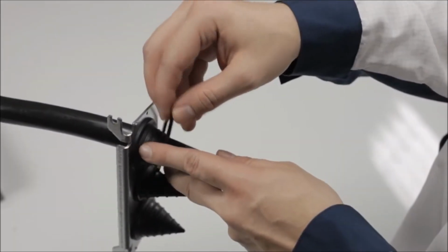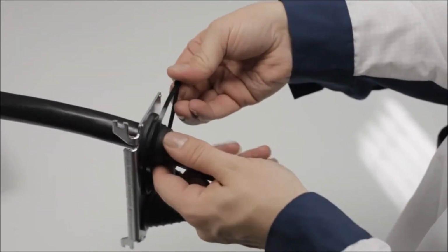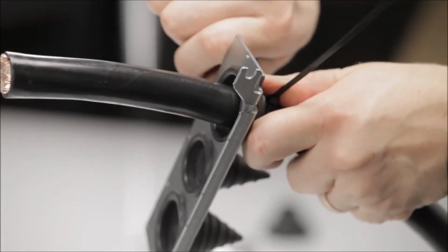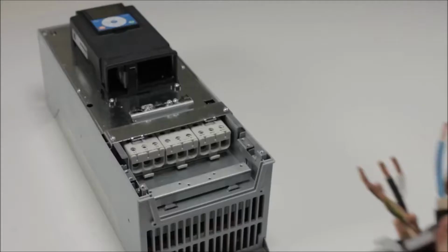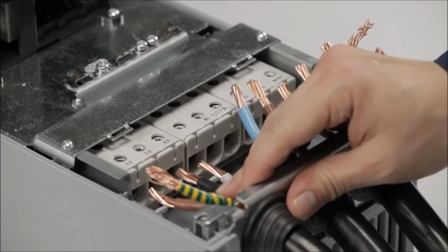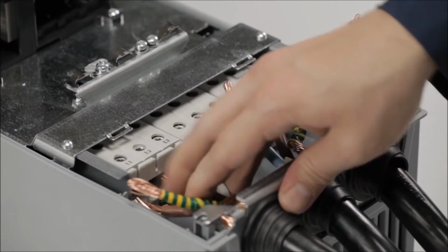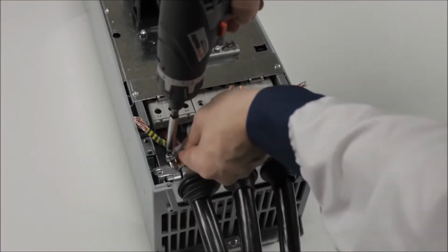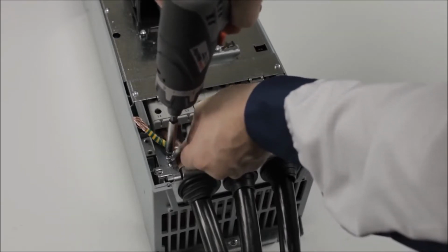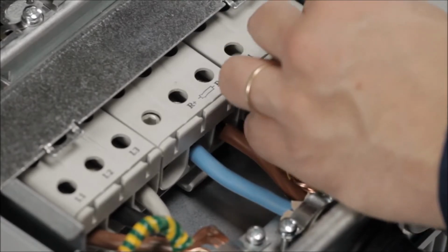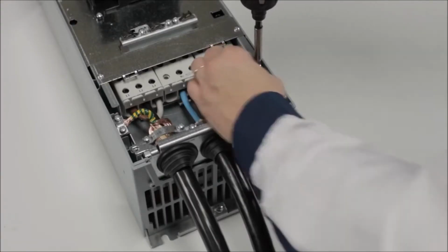It's now time to ensure the cables are connected to the inbuilt 360-degree grounding. This is another new benefit the VACON 100 offers, ensuring that no external cable clamps are required, which saves on costs, time, and space. Here's how you set it up. First, place the cable entry plate, complete with cables threaded through the grooves, onto the drive's frame. Now that the shield's 360-degree grounding has been established, the conductors should be ready to be connected.